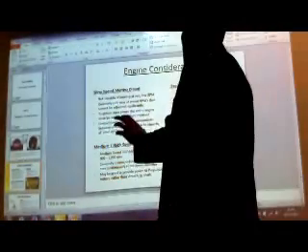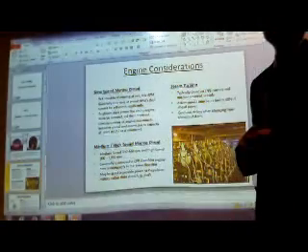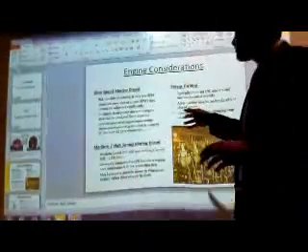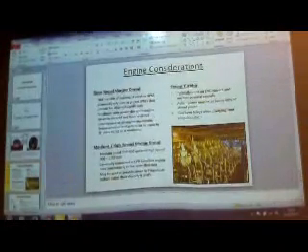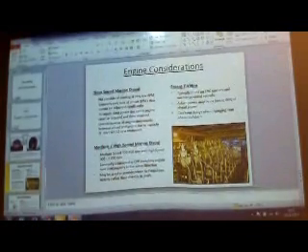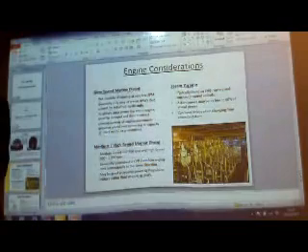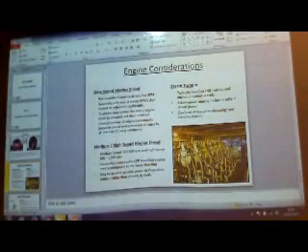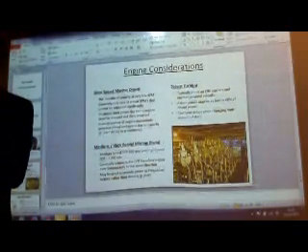Based on the vessel's propulsion needs, you will be putting the engine on the ship. Some would be a slow speed engine for a deep sea vessel which is going to run for a longer duration of time. We do not need very high maneuverability, but we need very high efficiency. It's a give and take between maneuverability and efficiency. And you need to use the engines, need to use the control. How often do you need to control it?